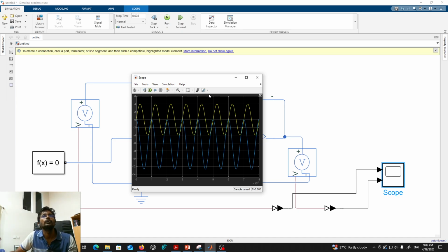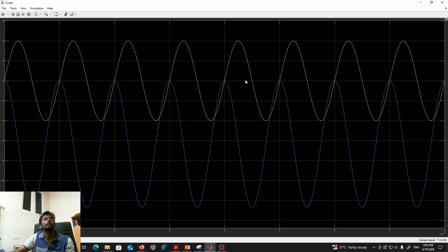Okay, so finally, we have got this as the answer. This is the input voltage. If you see, the peak is 4, and this is 0.008, which means this is like 8 milliseconds. Since it's 1000 hertz, within 1 millisecond you could see one cycle, right?